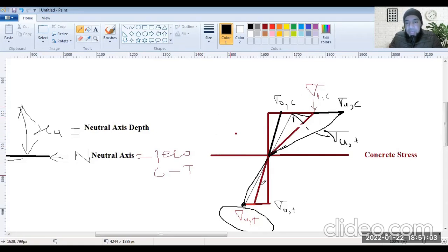तो पहले आपका टेंसाइल फेलियर हो जाता है for concrete in tension side. So that will happen first. If you take it as similar triangles, you can see that it's happening first. Then you will get the linear point for under compression, which is the yielding, or below that the elastic point. And then you will have the final failure.